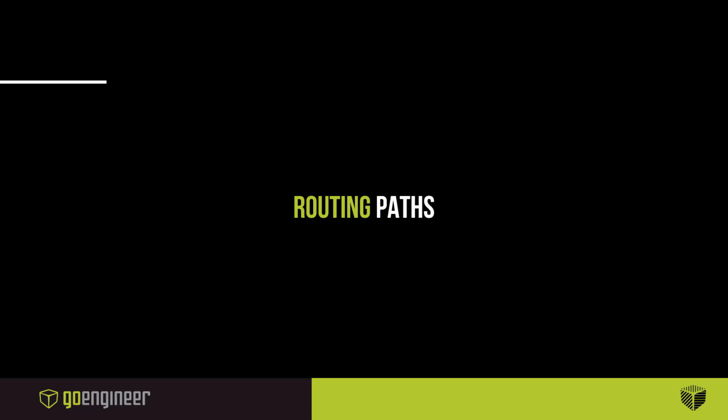So wires can route automatically from point to point, but sometimes you want to just suggest that they go a specific way. So you can draw, with air quotes, a simple 3D sketch in order to direct where the wires should go. So the wires jump onto the routing path, get as close as they can to their destination, and jump off and figure out how to get home.